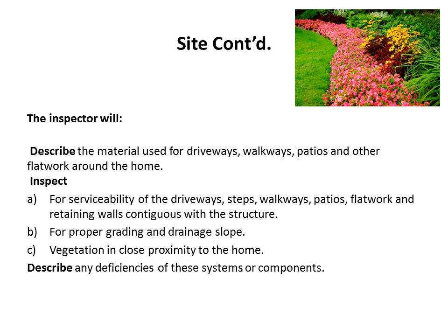The inspector will describe the material used for driveways, walkways, patios, and other flat work around the home. Inspect for serviceability of the driveways, steps, walkways, patios, flat work, and retaining walls contiguous with the structure, for proper grading and drainage slope, and vegetation in close proximity to the home. Describe any deficiencies of these systems or components.